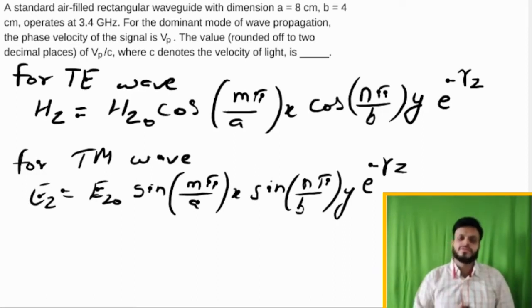So now let us first discuss why I am not considering Ex, Ey, Hx, Hy components, and I am only considering Hz and Ez. Basically, whenever a wave is traveling in some direction, we need to have some non-zero component in that specific direction. If, let us consider the TE wave condition, if I am saying z is equal to 0, then already for TE wave Ez is 0.